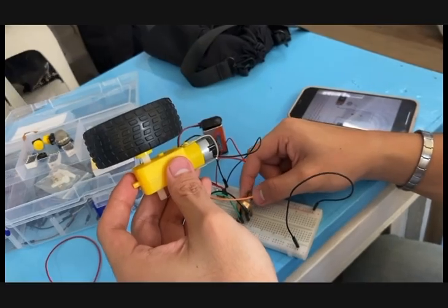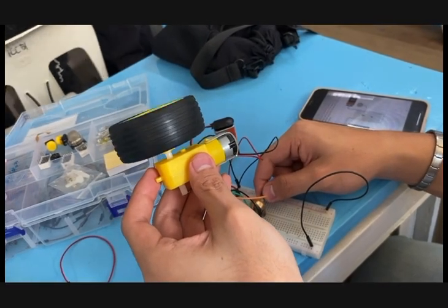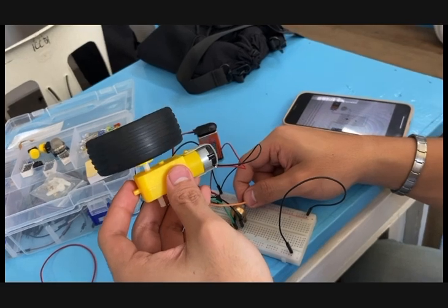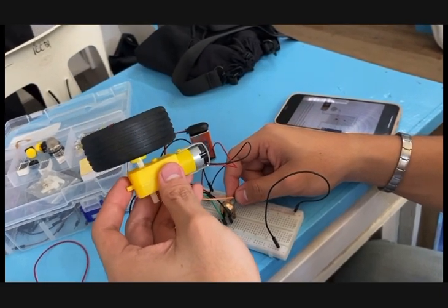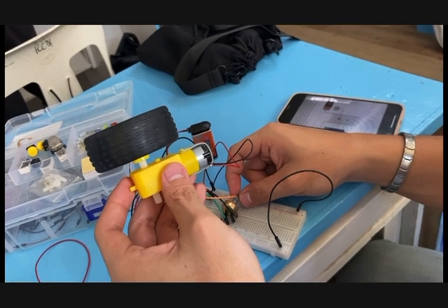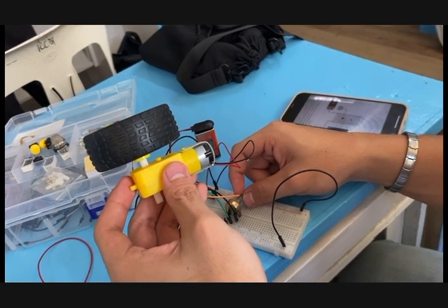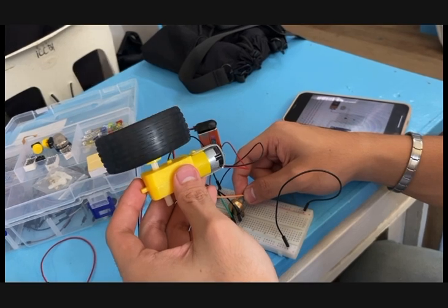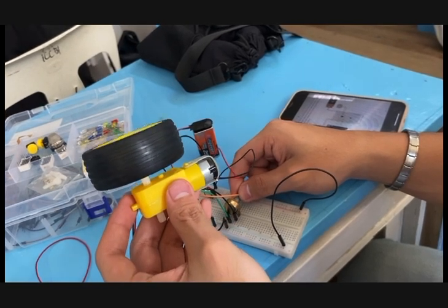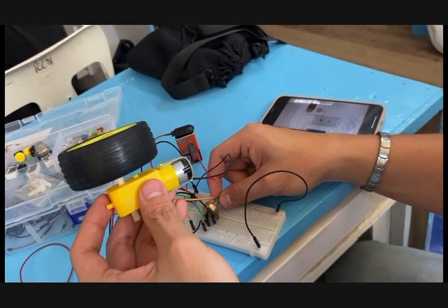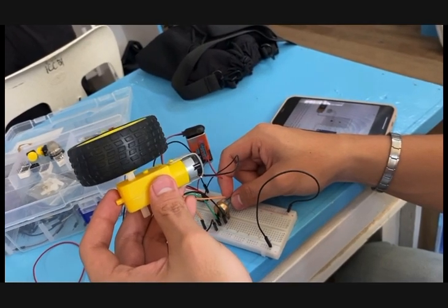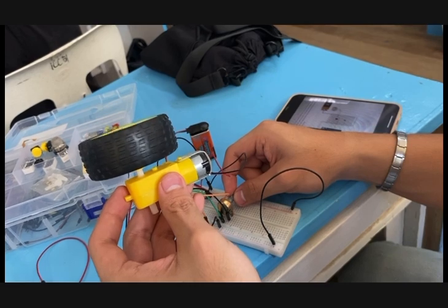We use a potentiometer and MOSFET to control the speed of a DC motor through PWM signals from the Arduino. Turning the knob changed the motor speed from slow to fast. We had unstable speed control at first, which we solved by securing the potentiometer connections. This setup can be applied in fan speed controllers, electric vehicles, and robotics systems.